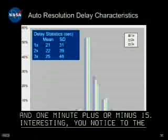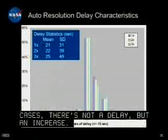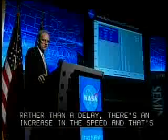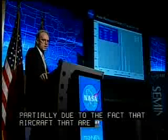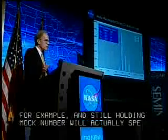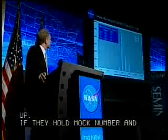Interesting, you notice that to the left of center, in some of the cases, there's not a delay, but an increase. Rather than delay, there's an increase in the speed, and that's partially due to the fact that aircraft that are descending, for example, and still holding Mach number will actually speed up. If they hold Mach number while they're descending, they will speed up and get to the end of the trajectory sooner.